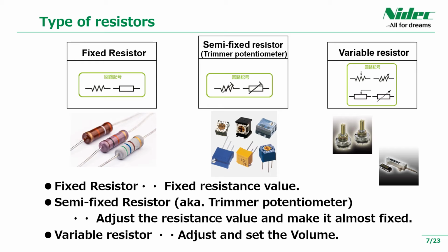On the other hand, a semi-fixed resistor is a part for trimming that removes individual differences due to variations in other parts by adjusting the resistance value of the circuit inside the device. Therefore, the number of times for setting will be minimal.